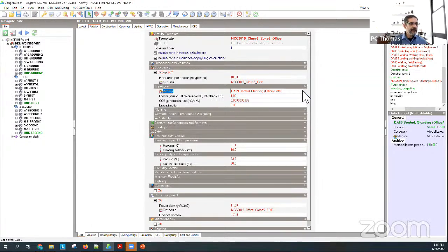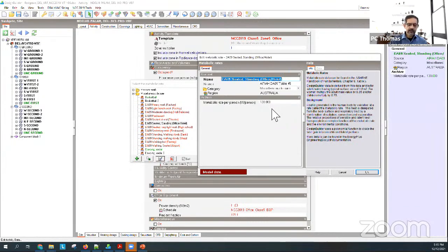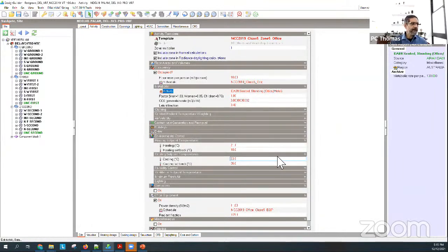And what we've been told is that for us, we have to use a value of 130 watts. Okay, so each adult male will produce 130 watts of heat. Now, all this heat is not straightforward heat which you can change into temperature. Some of that is what we call latent heat, or humidity. Okay, and that 130 watts, you can see that on the side here.